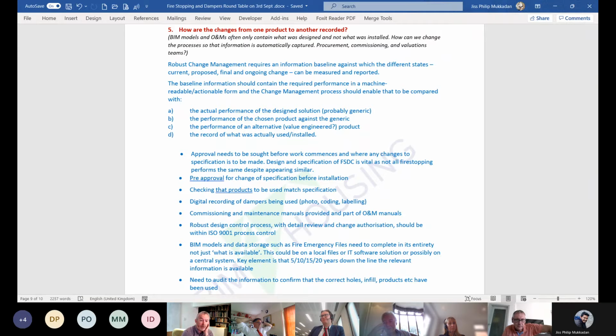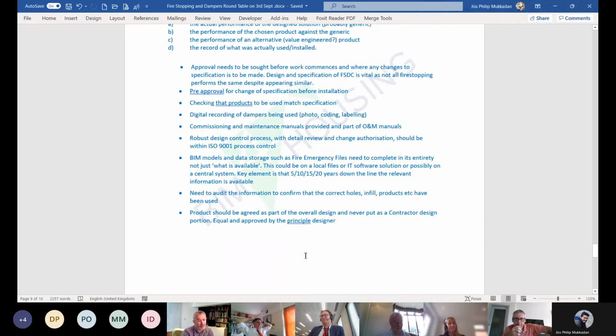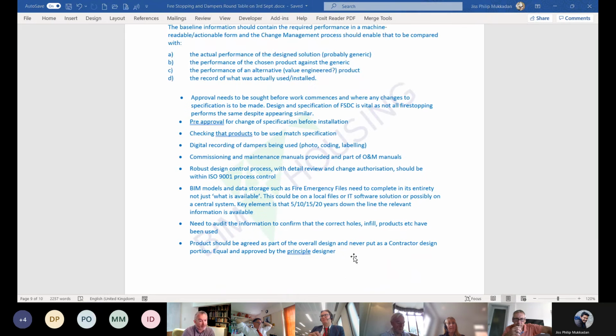The new BSR requirements, which if they come into force from April of next year, I think will significantly help that for projects and buildings that come under its focus. As we understand it, what will happen there is you will get a building regulations approval for detailed specification requirements on all elements of work. And should you then change or vary a product, you have to resubmit your building regs application. That puts a huge emphasis on getting your building regulations applications correct, and also puts a big timeline in your program for addressing those concerns.